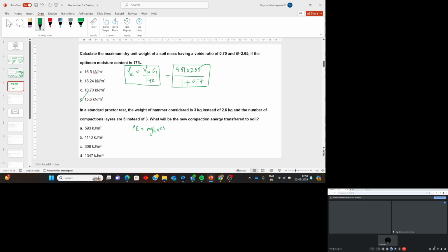How many times are you doing it? You are giving 25 blows. Yes, sir. And how many layers? Either it is 3 or 5, here it is 5. Now, in the standard Proctor test, the height of fall will be 31 centimeters.